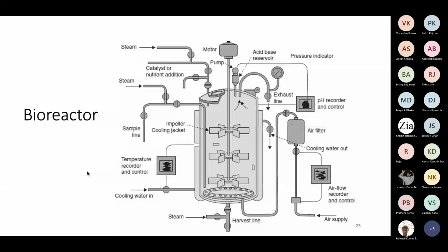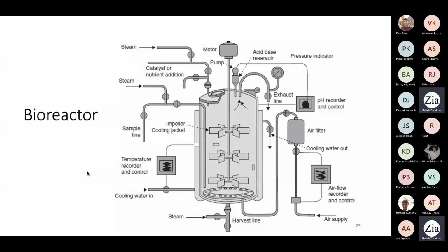So if you have a bottom-mounted reactor, where the motor drive is mounted at the bottom, then you can easily remove the excess shaft length which is present in the headspace area. And whenever you remove that length, the weight of the stirrer automatically gets reduced. So to rotate the stirrer, you will require less power. So from a power consumption perspective, and also to avoid dead extra shaft length, for large reactors we prefer to use a bottom-mounted stirrer or bottom-mounted motor drive.